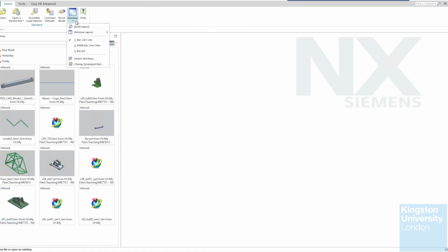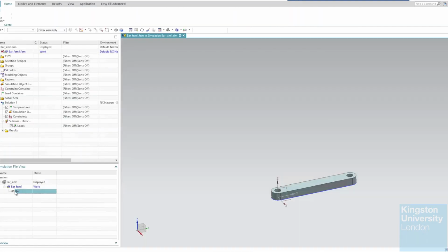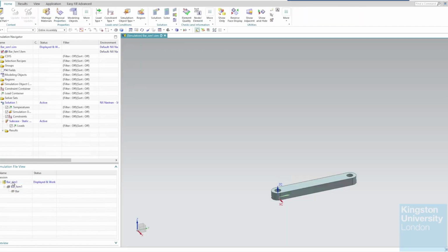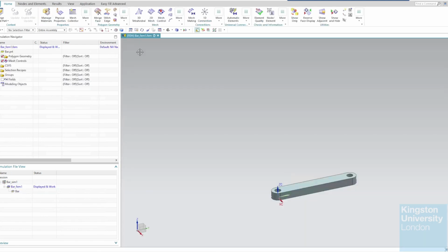Okay, so let me change my window and go to the power simulation we're working with. Okay, so in here, this is the finite elements modeling level, mesh level, simulation level. And you see actually once I click on those, the menu bar would change as well. Okay, so now what you need to do, we just need to mesh it first before actually we start the simulation. So I'm into the mesh level, so I double click to make sure I'm at the mesh level, and you see that actually it has the mesh sign next to it.